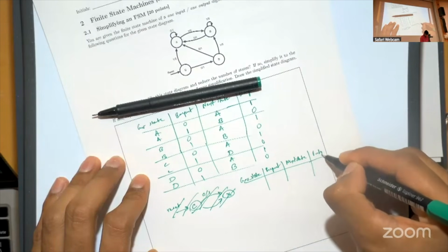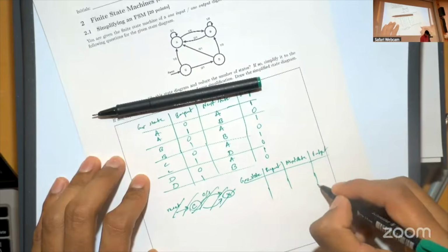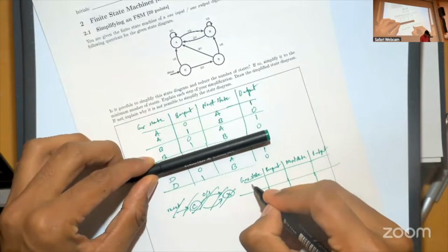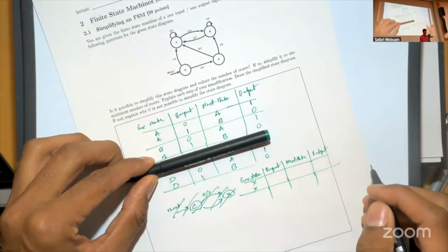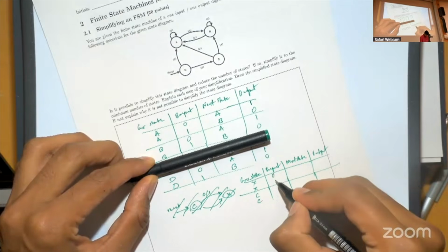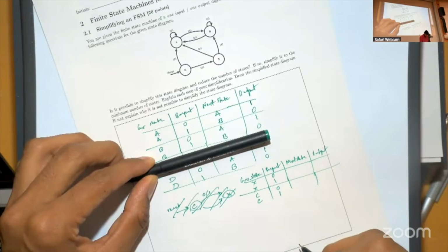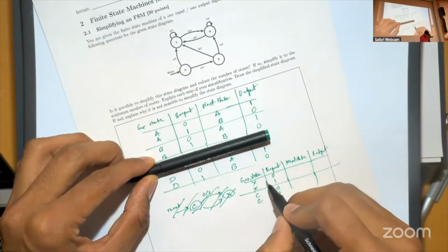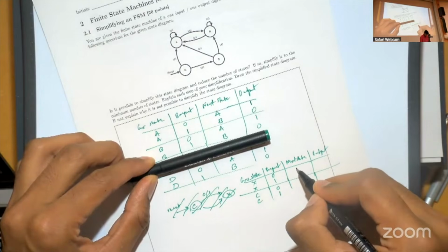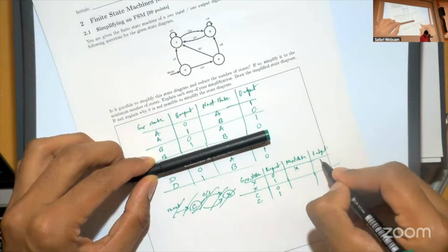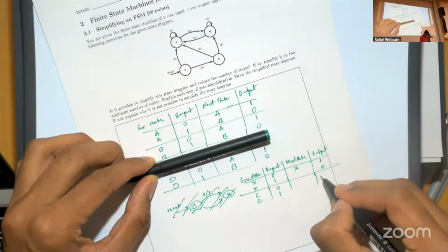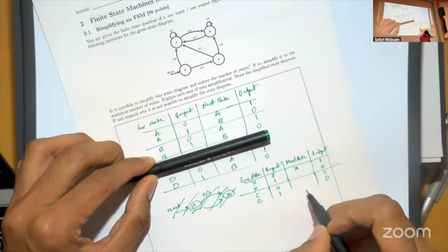And you have the output, okay? And we saw that we can decompose this down to 2 states. Let's say the new state is called X, okay? And we retain the C. And you have your inputs, 0, 1, 0, 1. For this state X and an input of 0, you stay in the same state, and you have the output 1. Your output is inverted for all cases. Let's fill that out first.